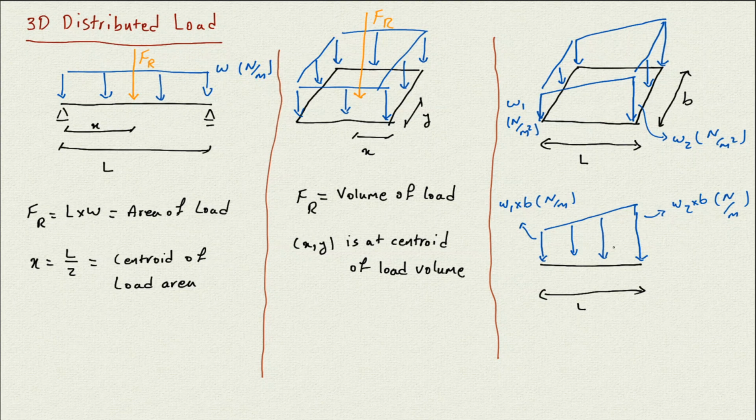And then when we have it in 2D format, we can do the calculation and find the resultant force on these 2D loads, which is going to be something sitting here as a resultant force. What we have done here is basically multiply whatever we have on the front face by the width, because there's nothing changing in the width. It's basically that volume that we compress onto the front face. So every load we have on the front face, we multiply by B, and then it becomes a 2D condition like that, and then like before we can solve it as a 2D problem, and we get all the calculations we need.